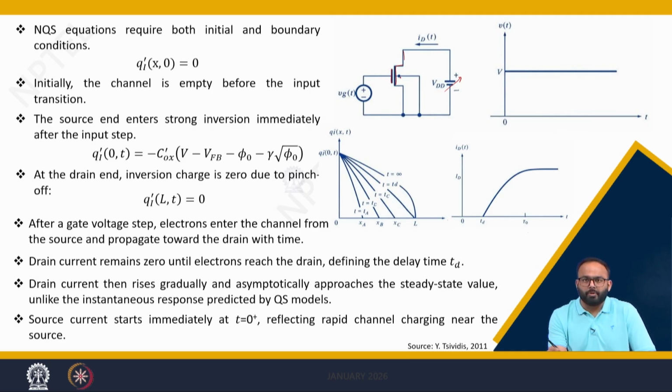You are in strong inversion and in deep saturation, meaning even when VG goes to its maximum value, you will be in saturation. That is the condition we are taking. Now every node voltage is fixed, that is VD, VB and VS; only VG is varying.